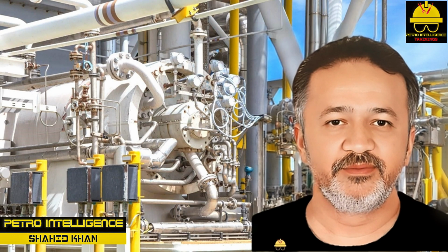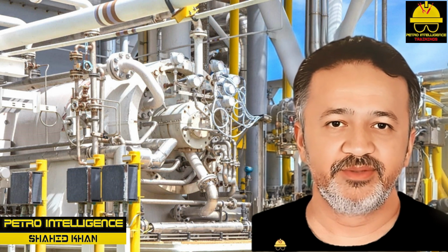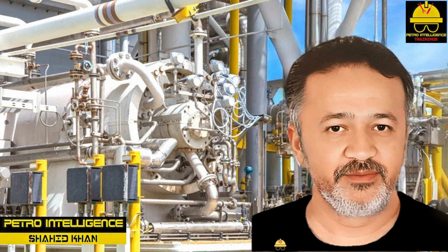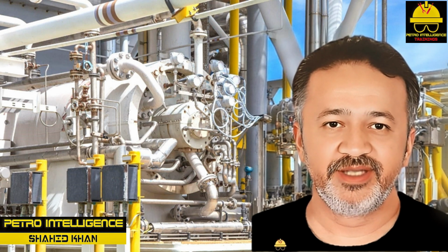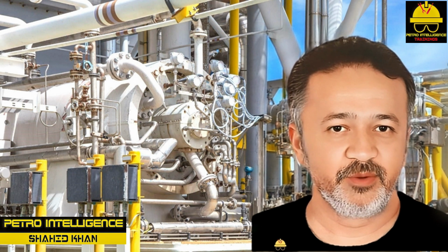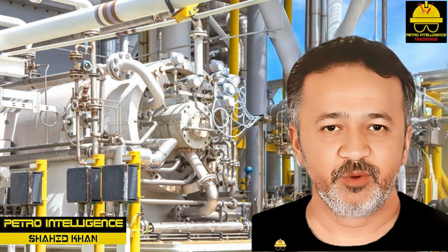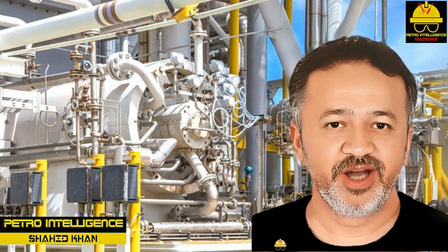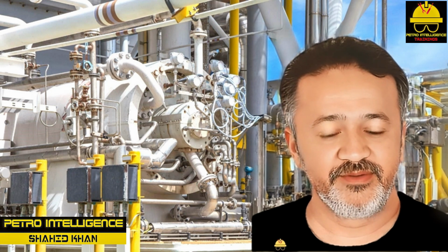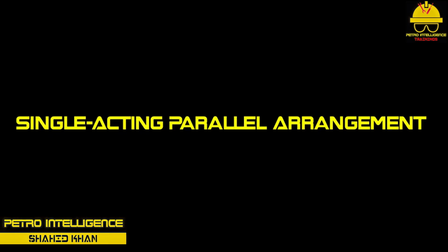Cylinder design. A cylinder's material is typically selected on the basis of corrosion resistance, thermal shock resistance, pressure rating, and mechanical shock resistance. Thermal shock is a form of stress resulting in metal fatigue caused by large temperature differences between a piece of equipment and the fluid in it. Common materials used to fabricate cylinders are cast iron, up to 1,200 psig, nodular iron, 1,500 psig, cast steel, 1,200 to 2,500 psig, and forged steel, over 2,500 psig.